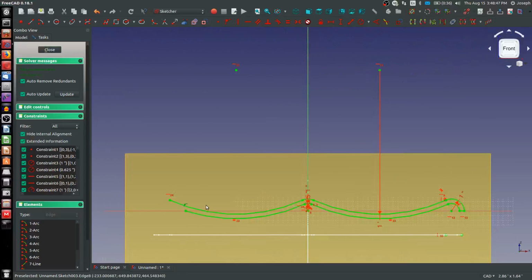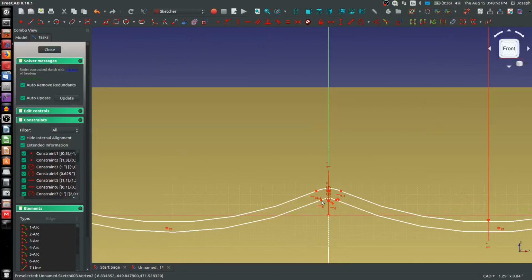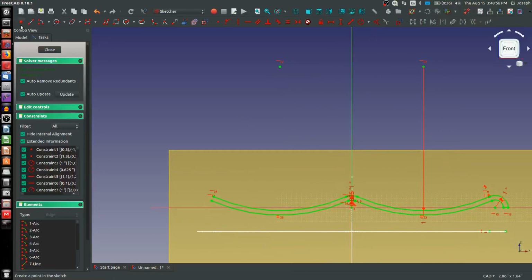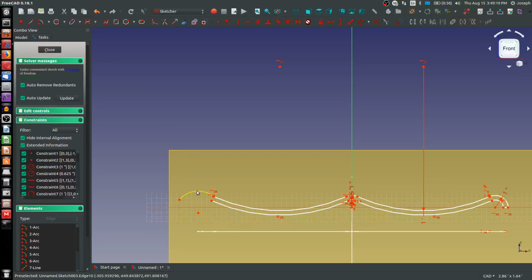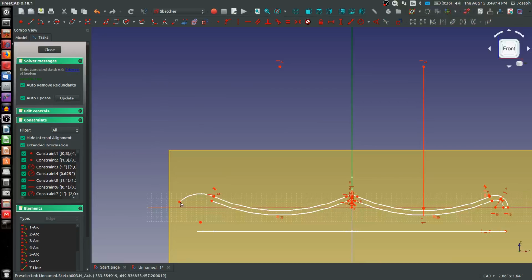And it added an auto constraint that I didn't particularly want, so deleting that, we use the H for horizontal, and we're fully constrained again. This, in my opinion, seems to go as fast as doing the mirror constraint and then adding in relations to fully constrain it. Tangent, I've never timed it though.